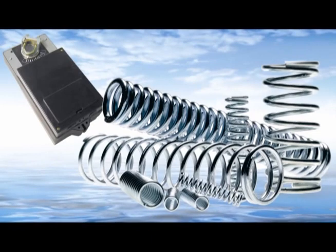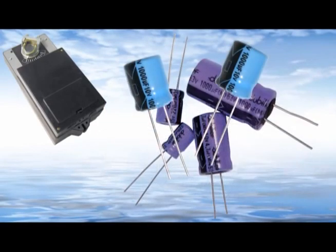To make a fail-safe version of a particular standard electric actuator, however, the torque had to be essentially doubled to overcome the resistance of the spring in addition to the load. Spring return actuators have been around for a long time, and building specs sometimes still state that spring return actuators be used. But a newer, more convenient, more durable, more consistent, and more energy-efficient solution for electric fail-safe is to use capacitors instead of springs.